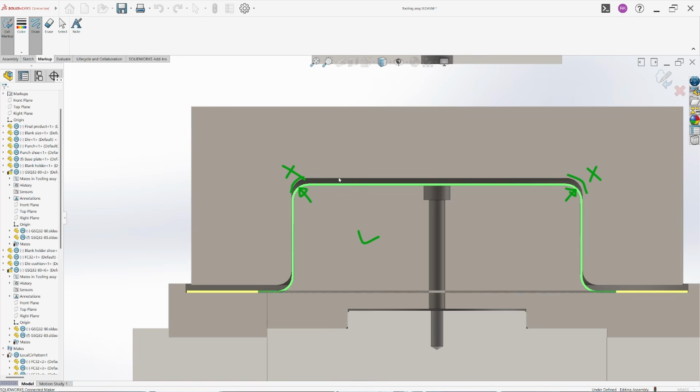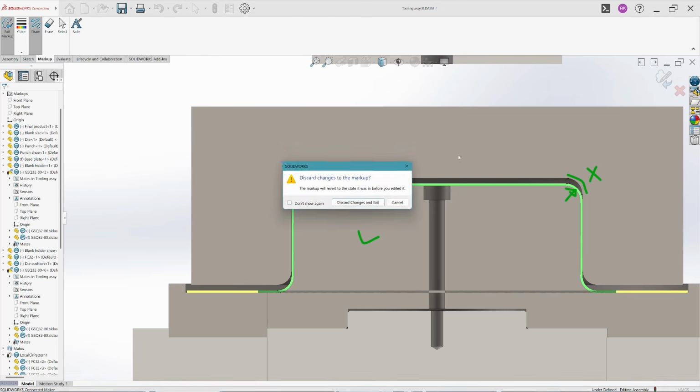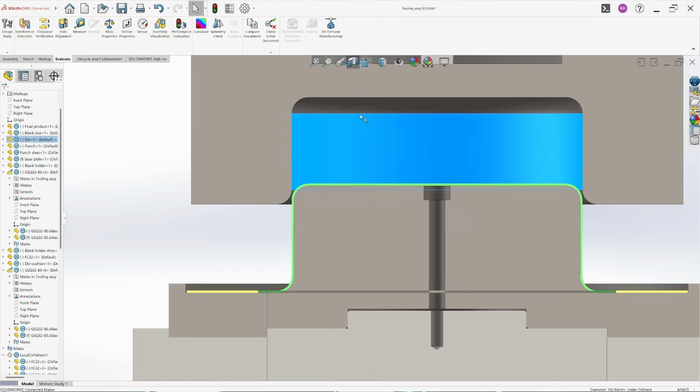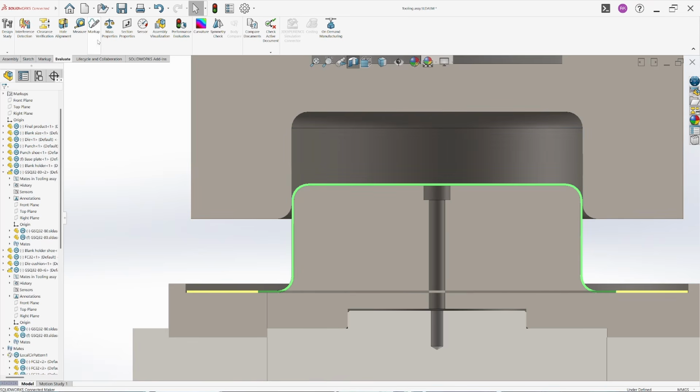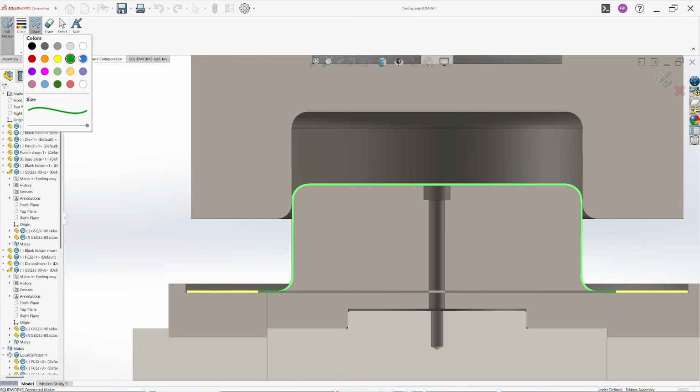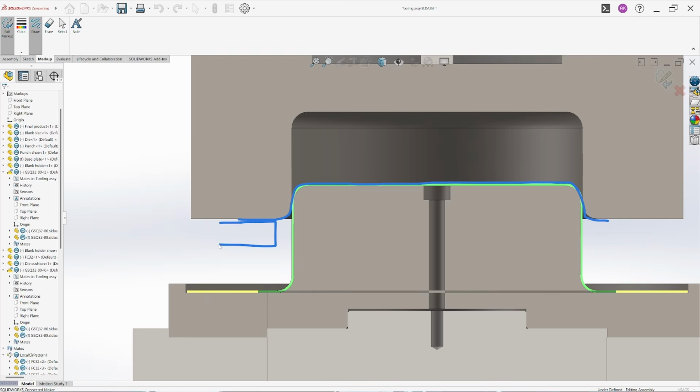If there is no radius, it doesn't matter, because the moment it starts forming, the sheet will go something like this, right? And as the blank holder will be there, and there is pressure over the sheet from both top and bottom, this radius is already made and controlled by the punch radius, right, not the die radius.